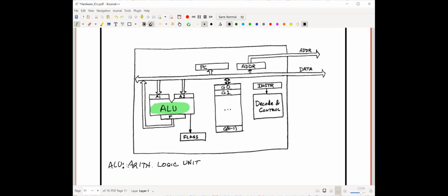After each operation, some flags may be set. For example, if an operation results in a negative number, like 7 minus 12, then a bit called the sign bit will be set. Other instructions can then test those bits. There are two argument registers, argument 1 and argument 2, and an output register R. Different chips have different flavors or variations of this.